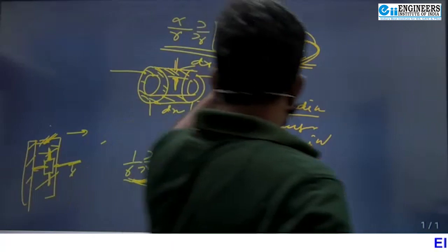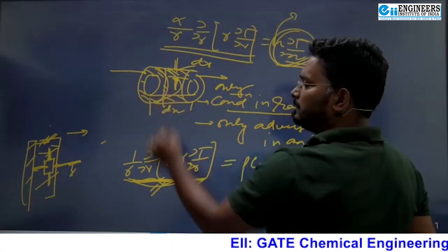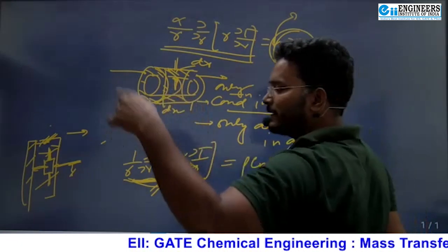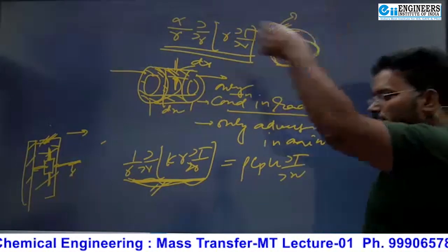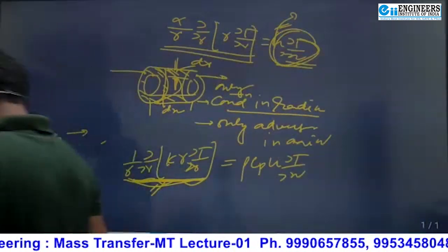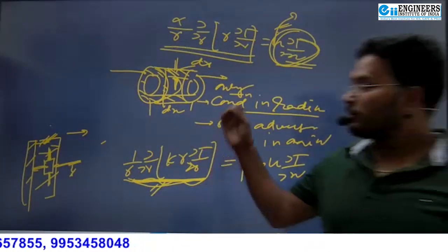And if this U is given to you as a laminar flow, now if the flow is laminar, fully developed, then what is U at any given point? This would be U max into 1 minus R upon R whole square. Isn't it? And this question has been asked in GATE also. How many of you are able to recall? Sir, I will make you recall everything, listen carefully.